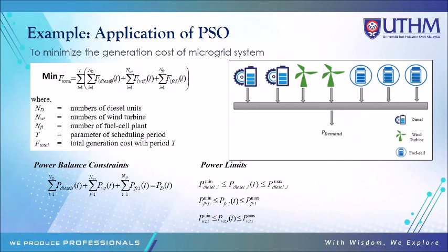In this situation, we have different units. Objective number one is cost, let's say dollar per kilowatt hour, for example. And number two, let's say we have emission, of course in tons of CO2 or kilograms. So, of course, we have different units. For solving multi-objective problems, we have different approaches. Number one, we can combine both objectives into a single objective by using the weighted sum method. That's the keyword, weighted sum method, for multi-objective problems.